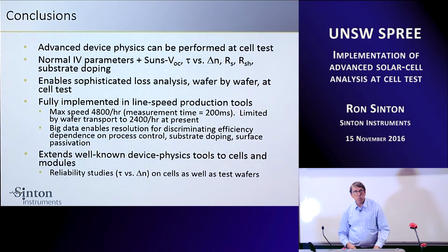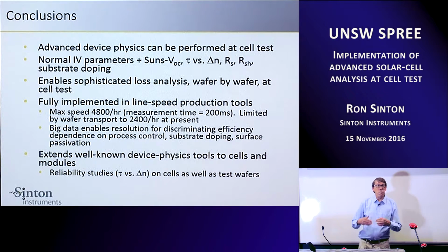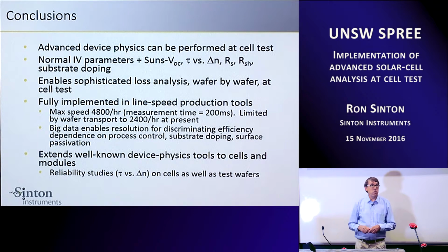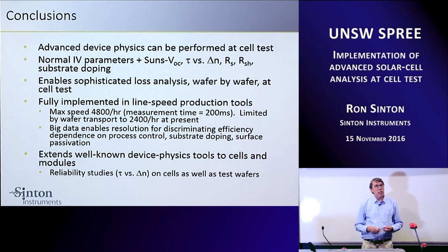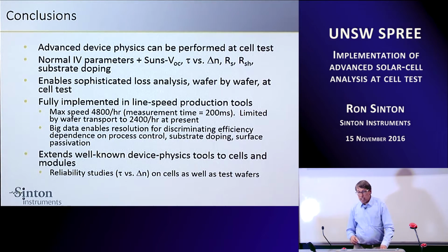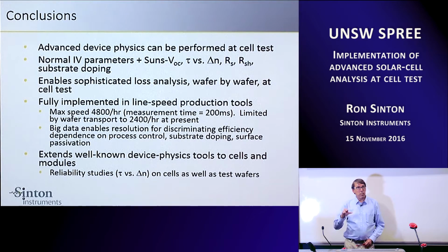Big data enables resolutions of parameters that were previously inaccessible. When you're in the lab, you have just a few wafers. When you're on the production line, you have millions of wafers, and you can really do fine analysis at a much more detailed level due to the big data sets. And so what we've done is show that you can extend the well-known device physics tools that we've been using for 20 years to the cell test.